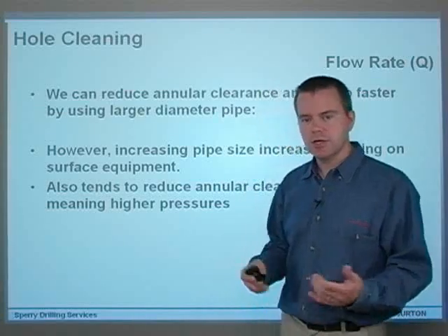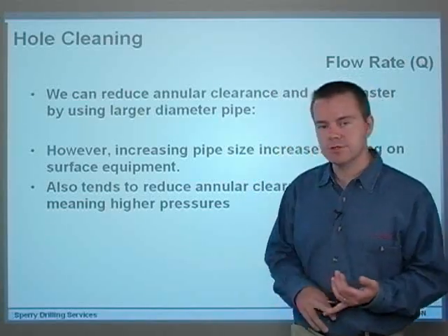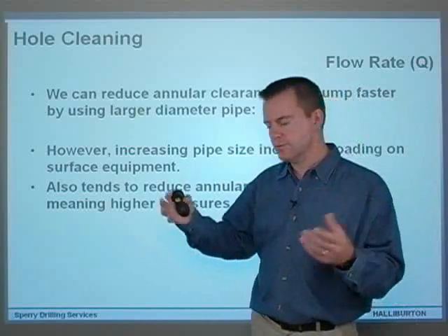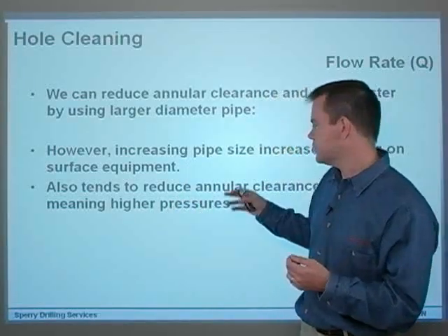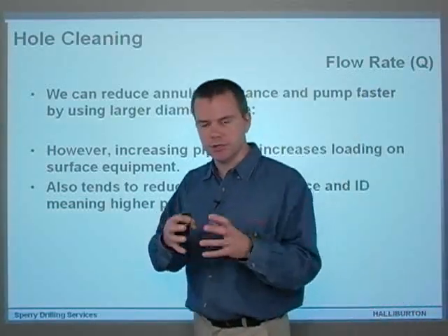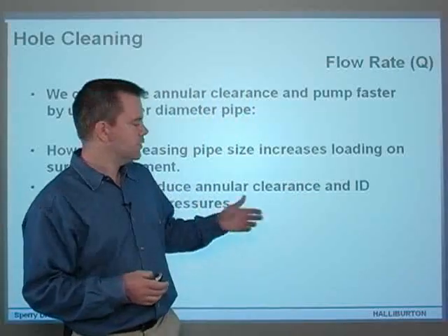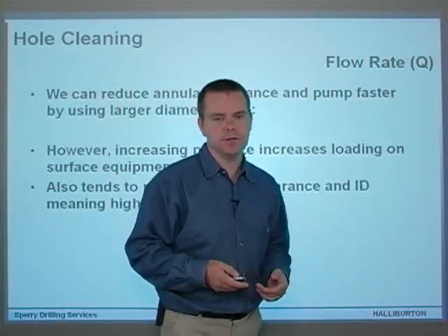Increasing the pipe size, as I said, increases the loading on the surface equipment. A larger pipe, smaller annulus, higher pressure in the annulus. Also, if the ID is increased because the pipe's bigger, then you could end up with higher pressures internally as well.